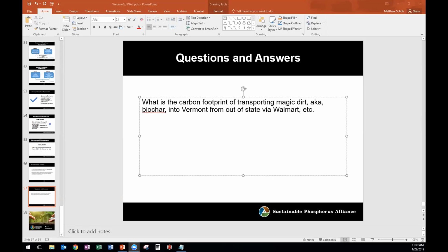Great, thank you. The second question, put up here, is how much polymer is used? Where does the polymer go after DAF, and what are the environmental impacts of it? It is a food-based polymer based upon potato starch, and it is used in the 1 to 3 milligram per liter range. The polymer, where does it go after the DAF process? It sticks with the solids is the answer to the question.